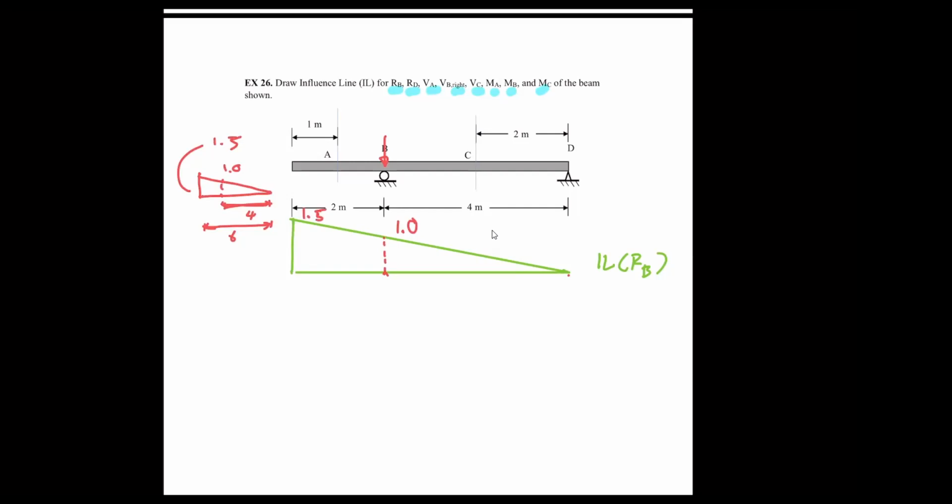Okay. And then, one thing I love very much about doing the influence line is that it shows the behavior of your structure. Let me go to the free page here. You can see if you have the beam like that. Let's begin from the simple beam. It stays the same, even with the cantilever portion. When I place the unit load here, the reaction is just going to be equal to that, right? That's how we get 1 at B.